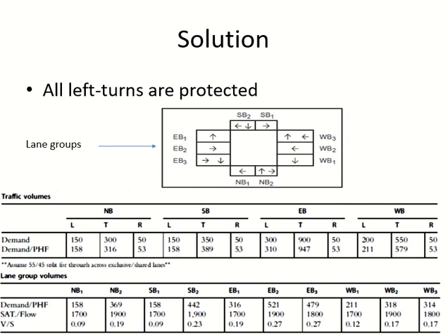That's very easy. Another factor which we did not use here was the heavy vehicle factor, because there were 0% heavy vehicles. But if they are there, then all of the flow rates must be divided by the heavy vehicle factor to convert to passenger cars, because capacity, saturation flow, everything is in passenger cars. So once you divided the flow for each lane group, converted it to flow rate and to passenger cars, then you take the ratio of the demand with the saturation flow rate.